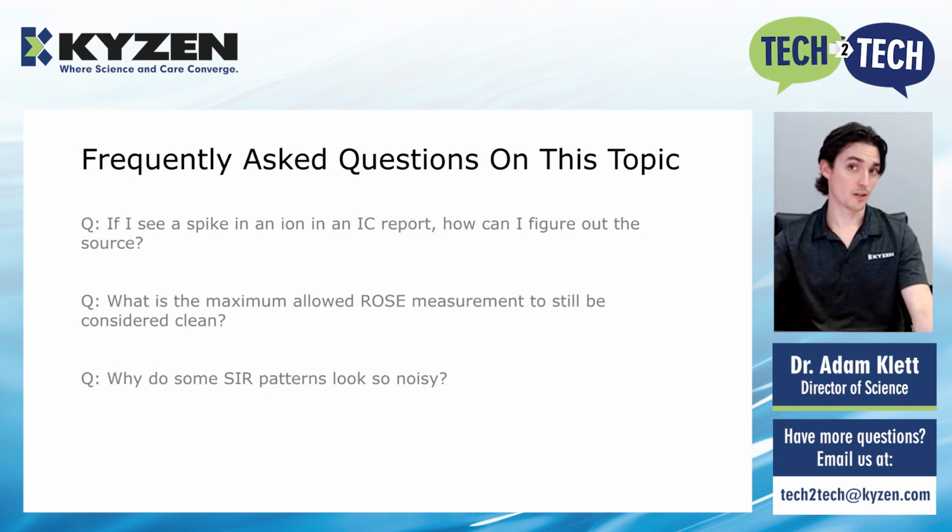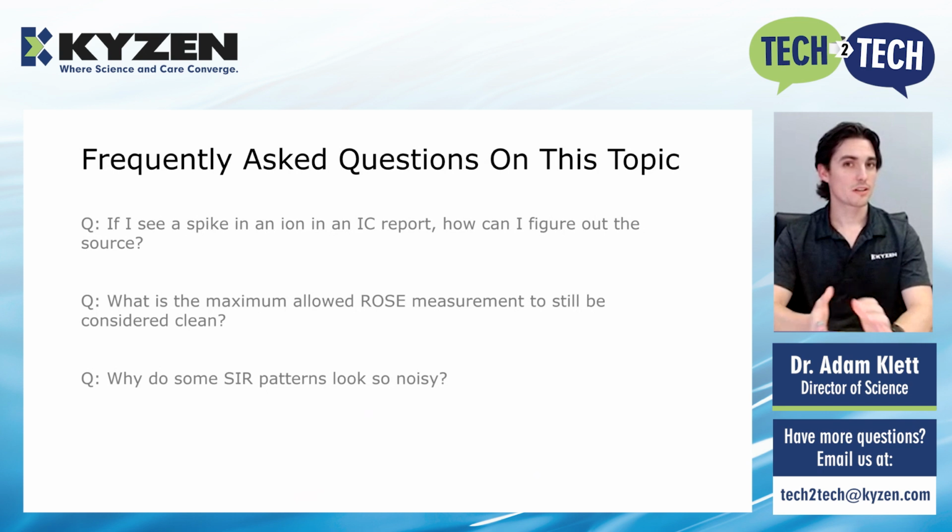All right, and the last question that we have is, why do some SIR patterns look so noisy and others look very flat? Well, there are a few sources of noisy SIR data. The first and most important reason, though, is that your board's dirty. Many times, sporadic and noisy data can be attributed to contamination on the board. However, if that's not the case and you've already ruled that out, there could be an issue with the experimental setup. For example, condensation dripping onto the test coupons from inside of the test chamber can cause spikes in the data.